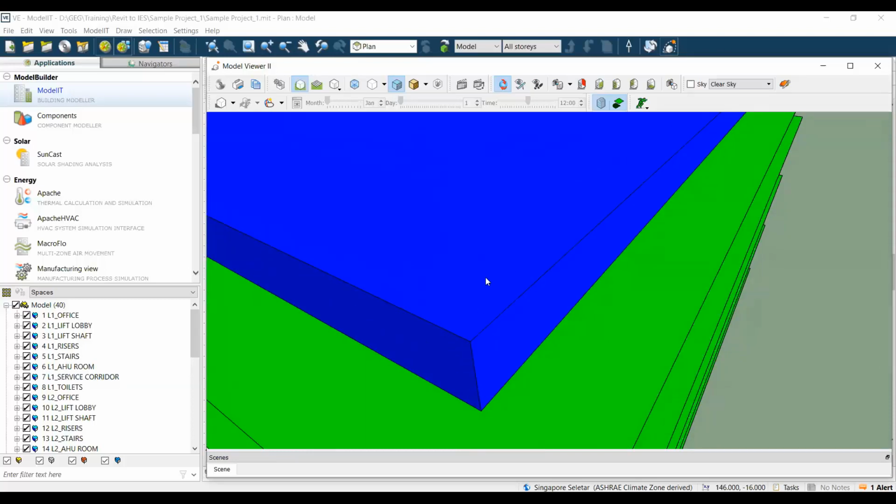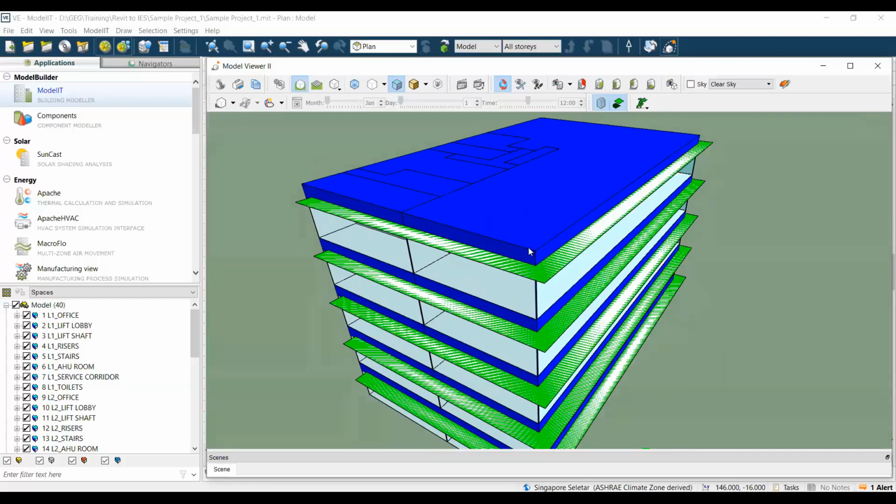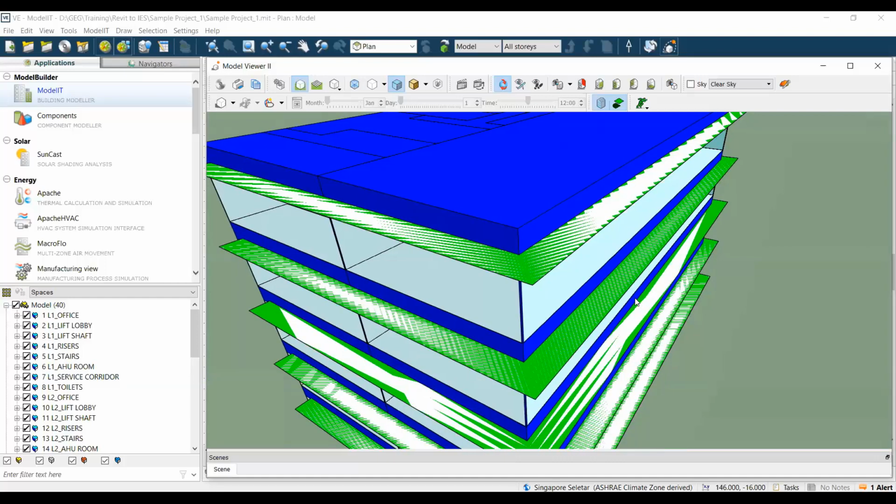Again, for the roof, we align to the center line of the wall. See how it's also just perfectly closing it up. Unlike if we align to the exterior side of the wall, you will see that there's something cantilevering out on all the sides, because it's considering anything outside of the wall center line to be a sunshade. So that's not what we want. We want something like this. It looks clean and no unnecessary local shades or anything. Okay.